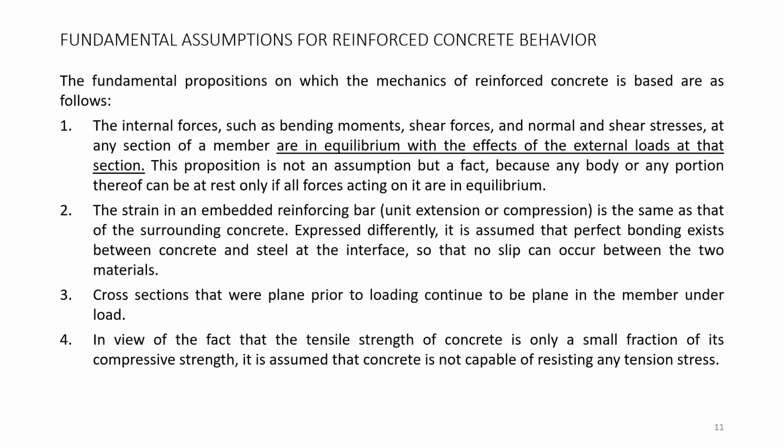On page 11 we have written 4 points here. Point number 1 is this: internal forces such as bending moment, shear force, and normal and shear stresses at any section of a member are in equilibrium with the effect of the external loads at that section. This proposition is not an assumption, but actually it is like this.